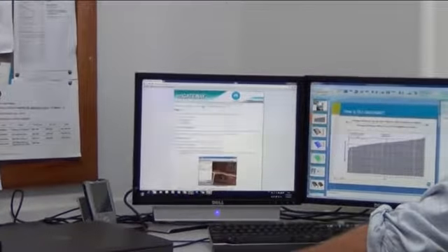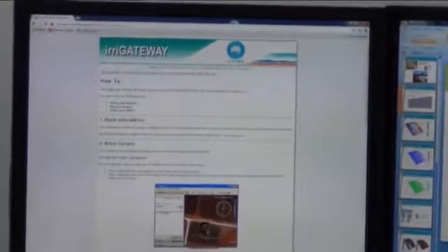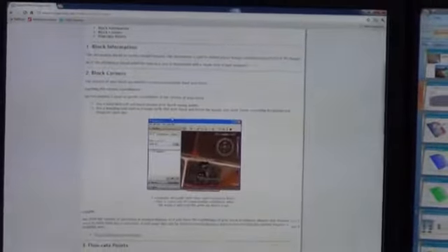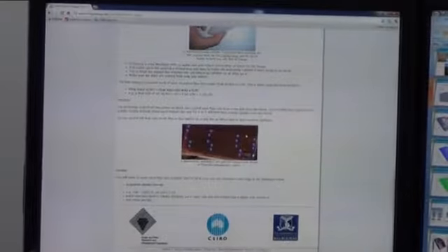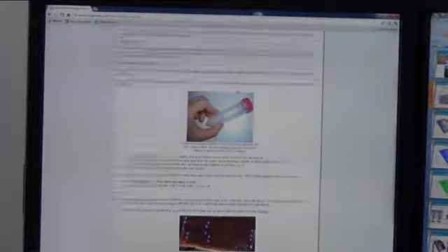So there's a how-to which will basically step you through the process which we've gone through on this short video introduction of taking block corner points, where we can either get them off Google Earth or with a handheld GPS, as well as measuring application rates spread throughout the particular irrigated field that you're interested in.